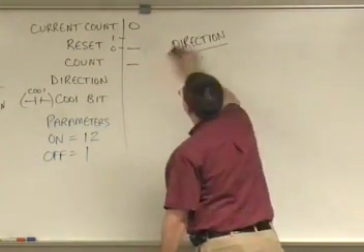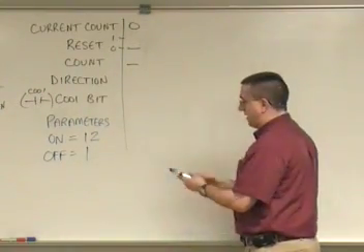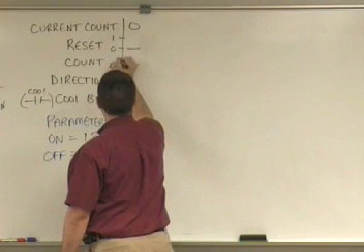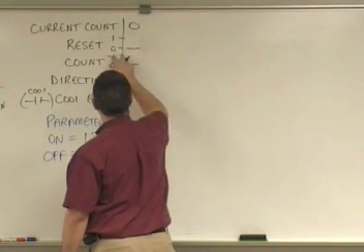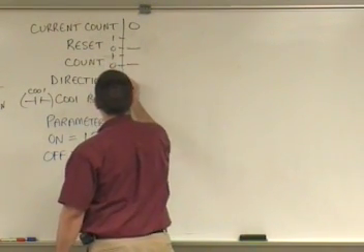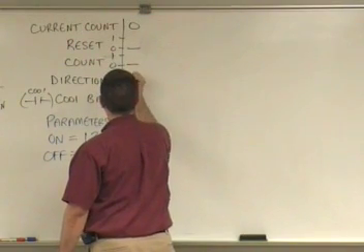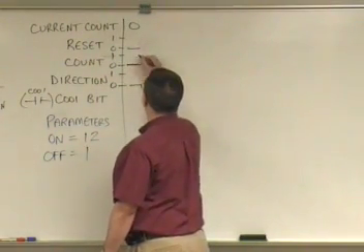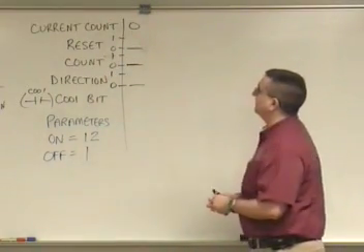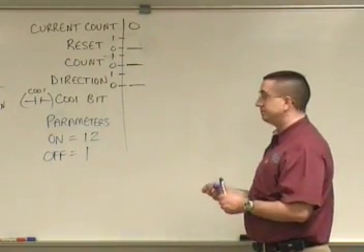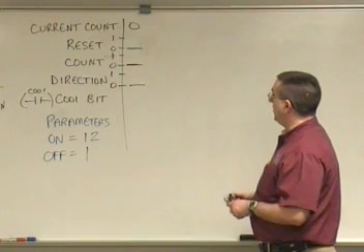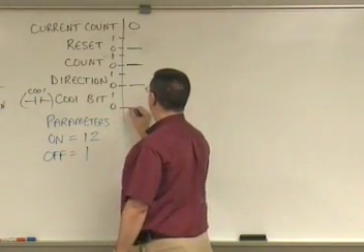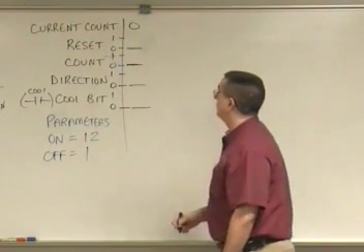So right now I'm going to start incrementing. If I'm going to be incrementing, I'm going to have my direction pin, which will be 0, 1 also. Initially my direction pin is going to be set to low. So right now everything is set to low. And therefore my C001 bit is what right now? It's off. It's a 0.